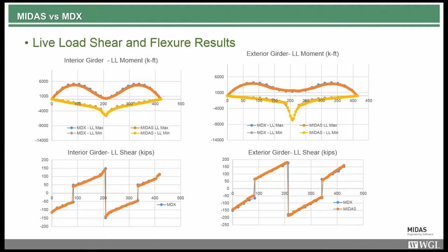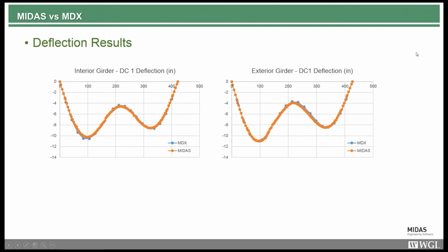As we go through and scroll on, you'll see that more or less, we're seeing the exact same results between the interior and exterior girders. One thing that's very nice, because we also have to provide camber information for the straddle bent, is that at the actual girder locations, we're getting very good comparisons between our calculated springs and MIDAS's 3D analysis software. So this gives us a lot of confidence that the camber information provided for the straddle bent will also be accurate and reflect the final conditions out in the field. And with that, I have finished my presentation, and I'm going to go to some questions.